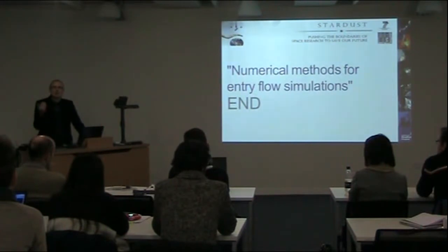An unstructured mesh is, for example, a triangular mesh, which is not a regular grid, and basically you do not know a priori which is the neighboring node, so you have to store also which nodes are connected.